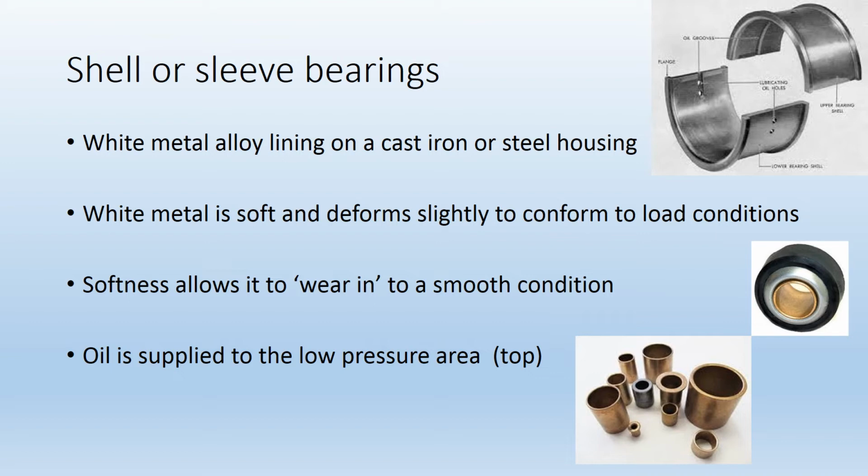One thing you'll note also in the previous slide is that oil is introduced on the low pressure side of the bearing, and in this case the oil supply would come in from the top. So the oil is always being supplied on the low pressure side of a bearing. It's not going to be introduced underneath the pressure area where that hydraulic wedging action is going on.